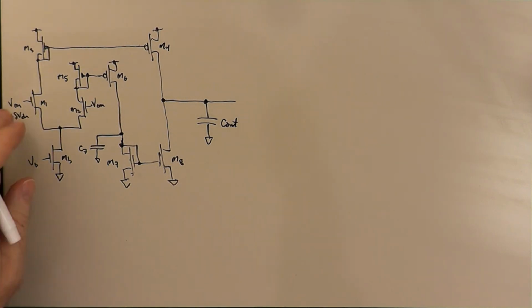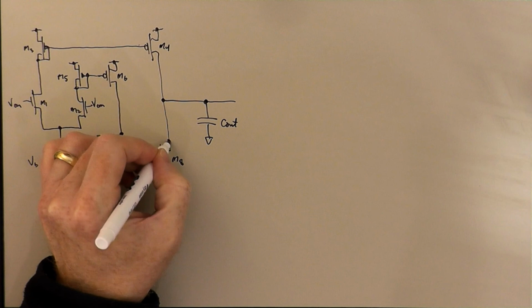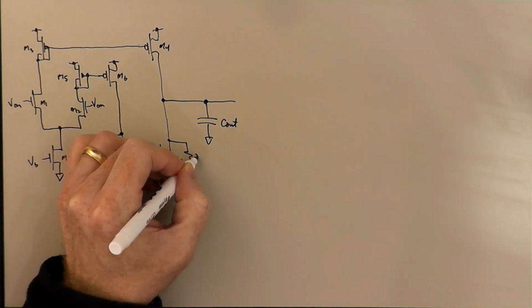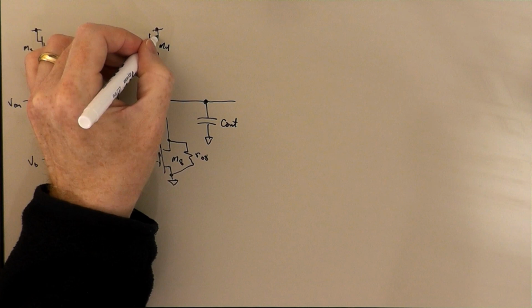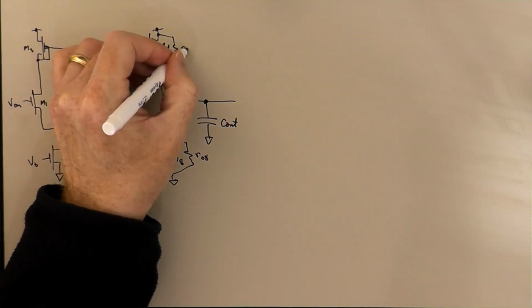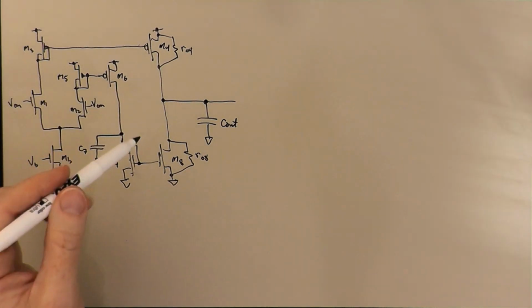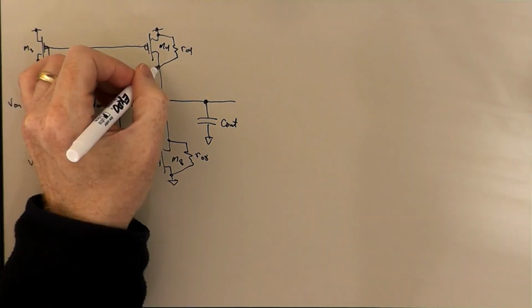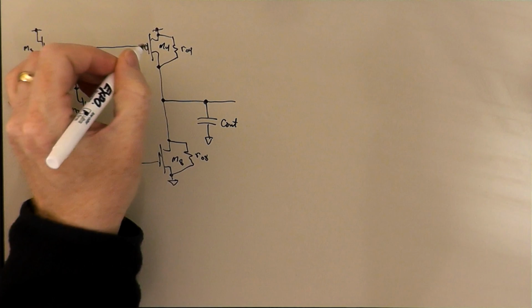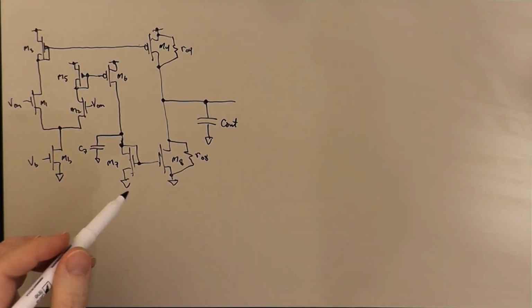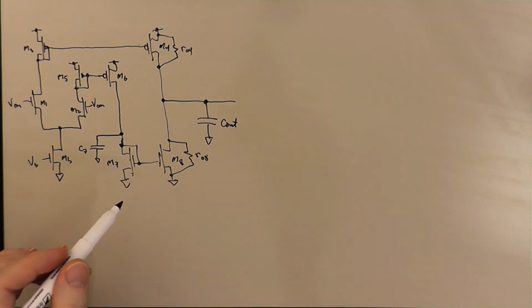Okay. So we're going to apply node fixing just like we've been doing and ask what difference the presence of this capacitor would make in our analysis. And the first thing I want to do is consider what effect C7 would have on the output impedance of the circuit. So we've had early effect resistors, RO8 and RO4, that we figured we needed to conclude that the low frequency incremental output impedance is not infinite to get a finite low frequency differential mode gain.